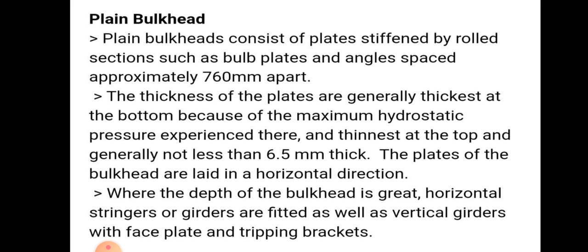The plates of the bulkhead are laid in horizontal direction. Where the depth of the bulkhead is great, then horizontal stringers or girders are fitted, as well as vertical girders with face plates and tripping brackets.